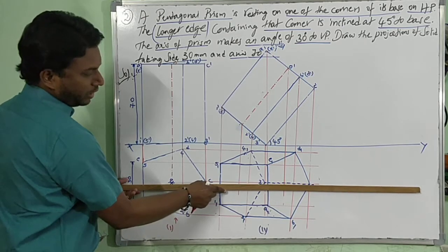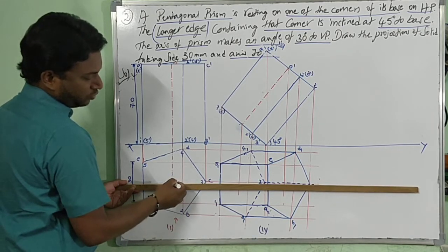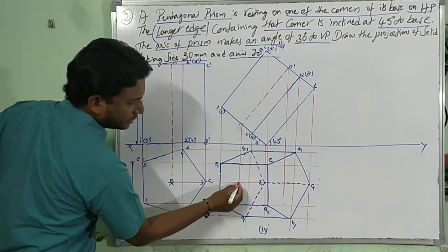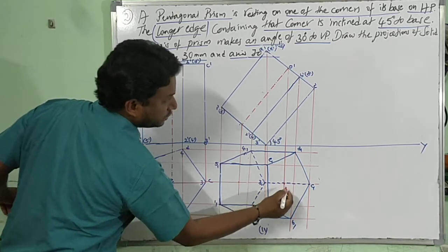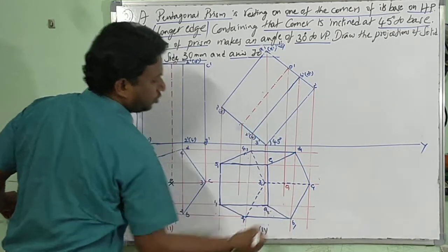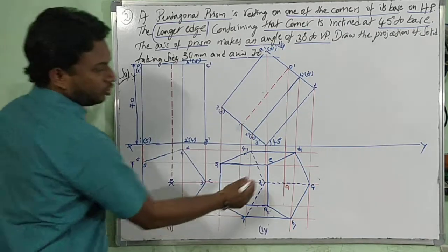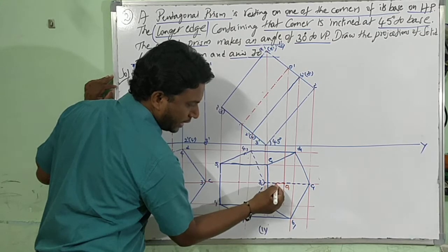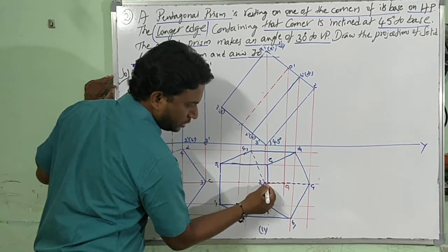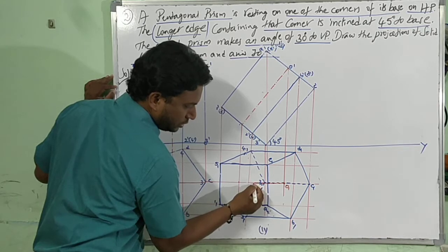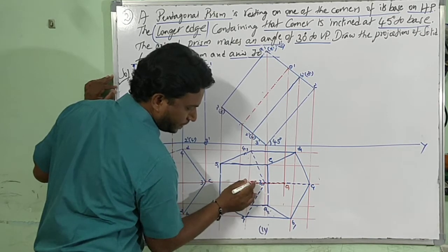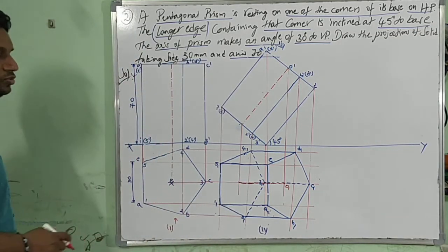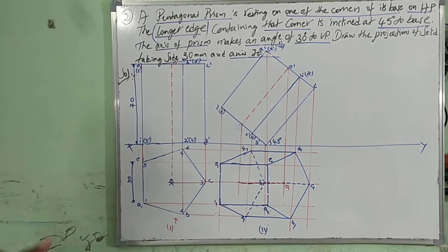the projector I have already drawn, which is through this O, passing through C. Now here come the intersection points, this one, this one. Now O dash becomes O1. Already you have drawn it hidden here, but still in that hidden dash-dot, dash-dot, axis line, you are supposed to draw the axis line on it again.